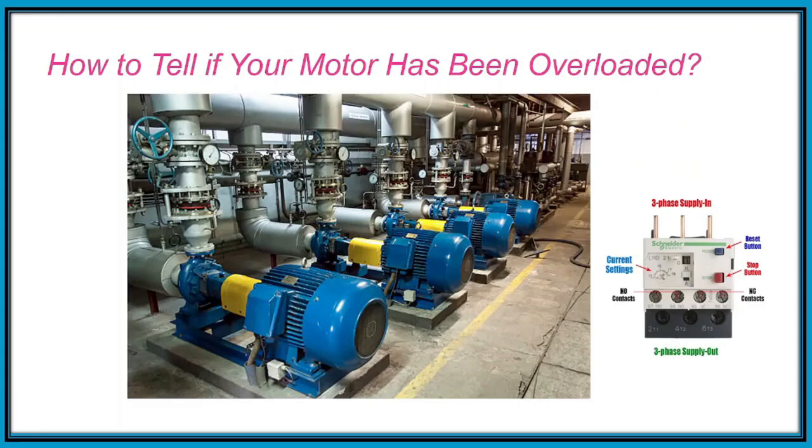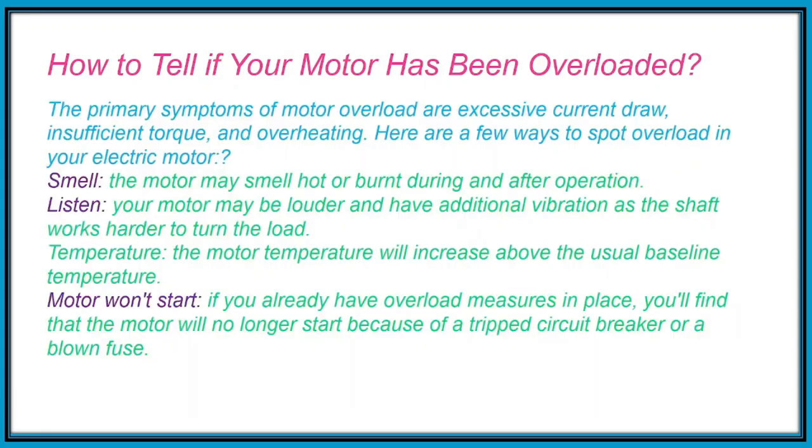How to tell if your motor has been overloaded? The primary symptoms of motor overload are excessive current draw, insufficient torque, and overheating. Here are a few ways to spot overload in your electric motor.